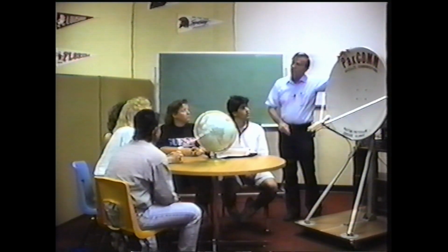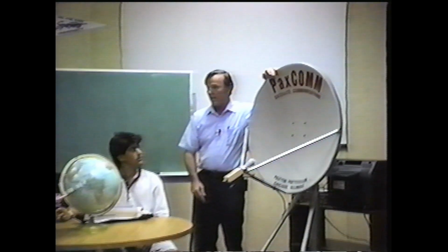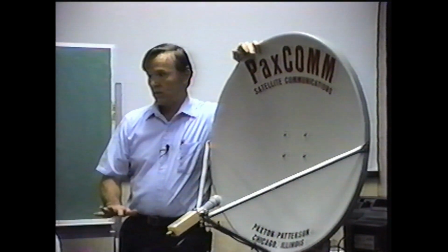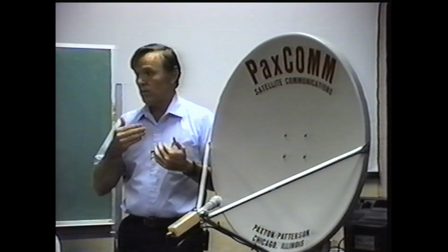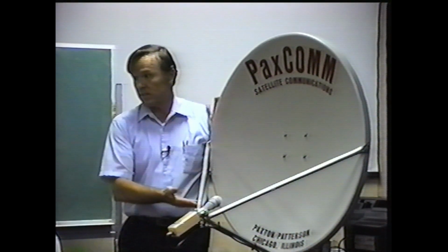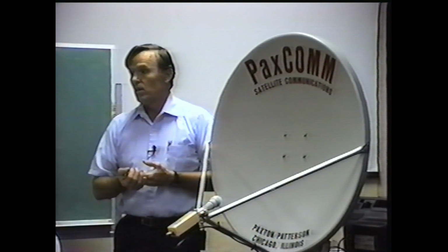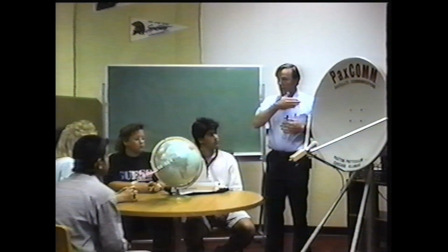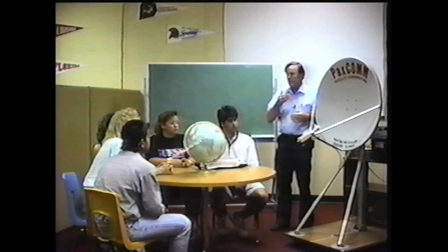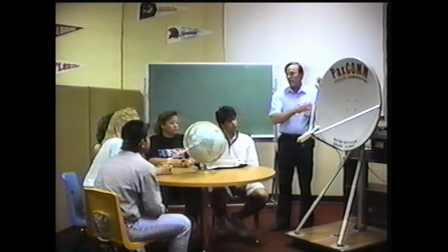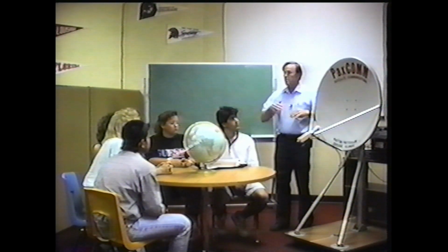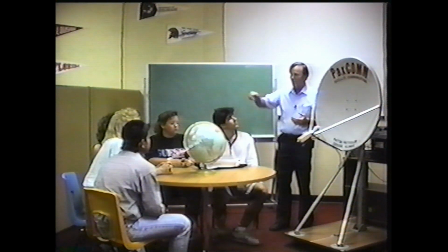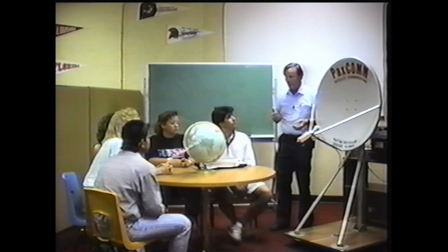Okay, probably your neighbor's system is a C-band satellite system. We have two systems of satellite broadcasting, or two different types of equipment. One is the KU band, which this is. And then we have the C-band, which has been in use over a much longer period of time. Now, the C-band satellite system operates at half the frequency, or half as high a frequency as the KU band. The C-band satellite system broadcasts on the same microwave channels as what all the telephone companies use on repeaters all over the United States.